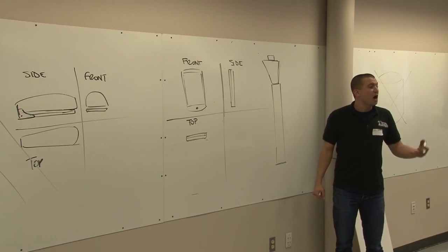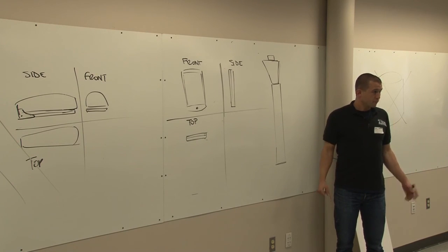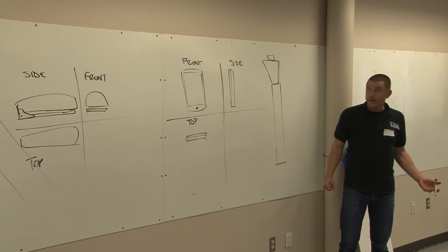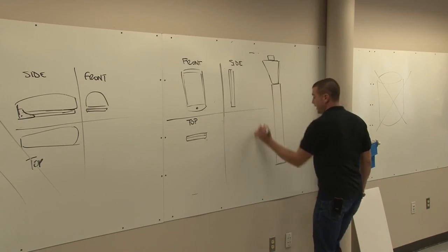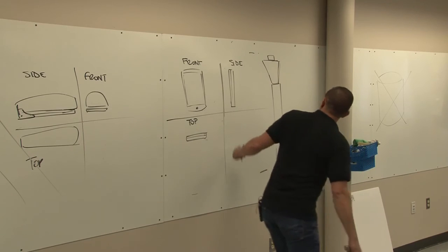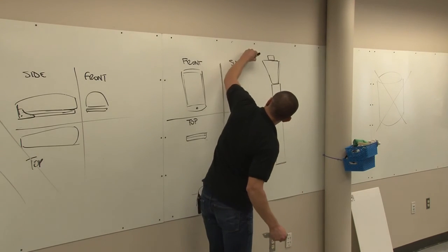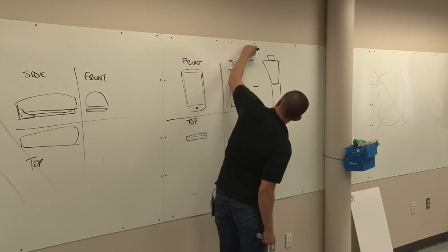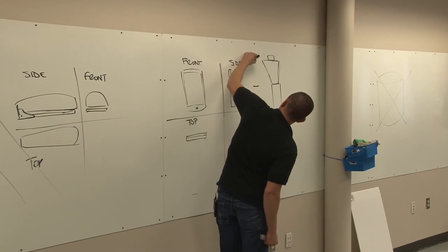But they're all kind of going along up and down. So I'm going to do like a compound dimension line. One line broken into multiple pieces. Let's say it starts at the top here, it ends at the bottom here, and it has a part here at that height. It's got another part here at this height. And I'm going to do little arrowheads between each one.